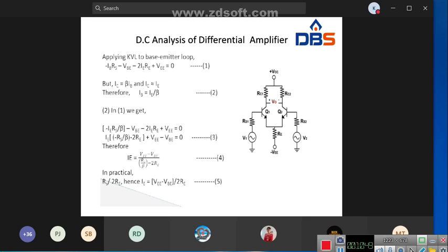We are having two transistors, so two resistors, that is RS1 and RS2. Simply we can take RS. The base current is flowing through RS, here at the base terminal. So the voltage drop across this resistor is IB into RS.